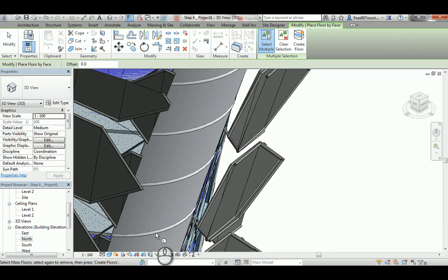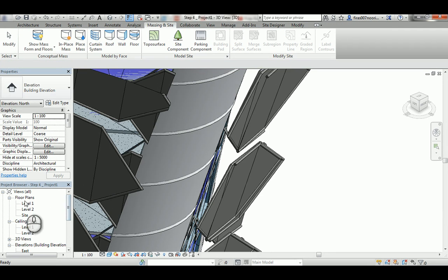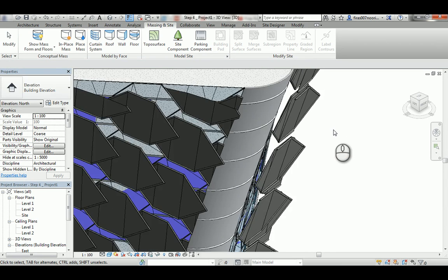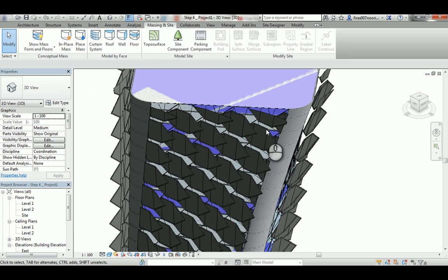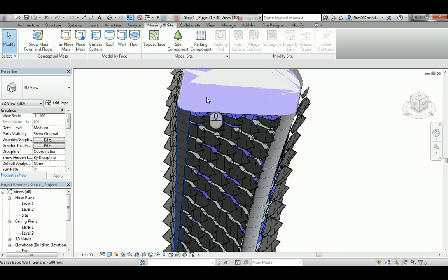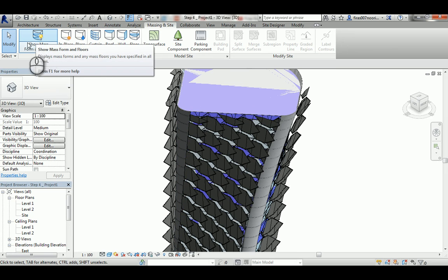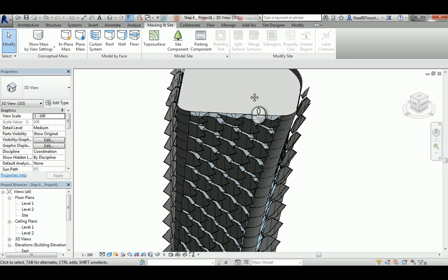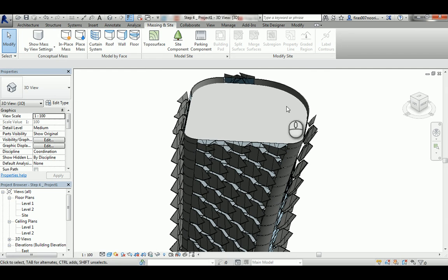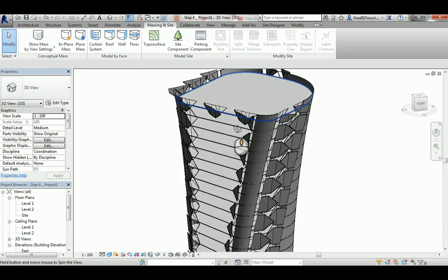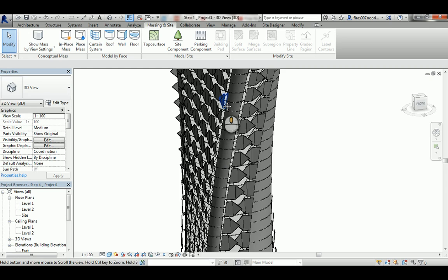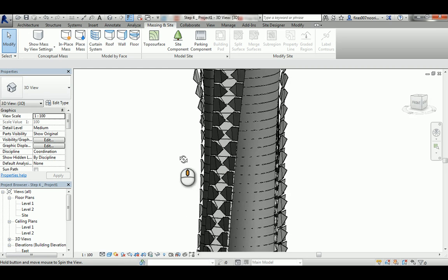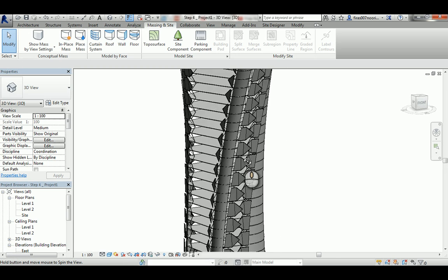We just created the floors for you, but if you look at the views, there are still no plans for that. To create those is a totally different thing. Anyway, before I do that, I always try to remind you to turn off this whenever you don't need it. And in this case, technically you don't need it anymore, because you created slabs and walls, and you have this curtain system. So it's a complete architectural building, ready to be documented or to finish the job with whatever you want to add for it.